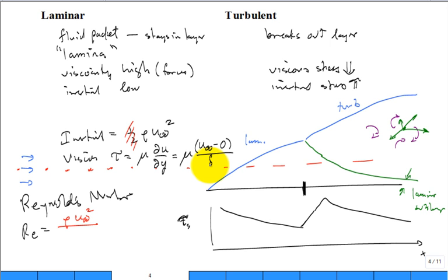Well, this is where it becomes more difficult, and that's why the Reynolds number doesn't break at 1 or something like that. It's hard to get a good length scale for true scaling. So what you do is you grab any length scale that's of value or interest or that's readily available. X, if you're doing flow over a flat plate, that's the distance from the leading edge.